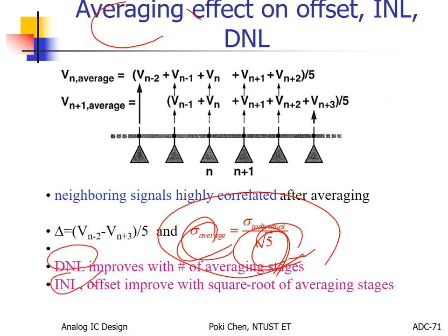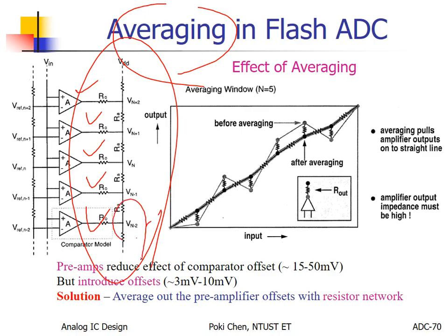Much better than before. But do you need to apply such a complicated R-ladder, C-ladder for your ADC design? Not necessarily. It depends on how good you need your ADC to be. Again, that is for high-end, very high-end ADC design. Otherwise, usually we don't pay such a price for your chip design because it is really expensive. You need a lot of resistors, a lot of capacitors.